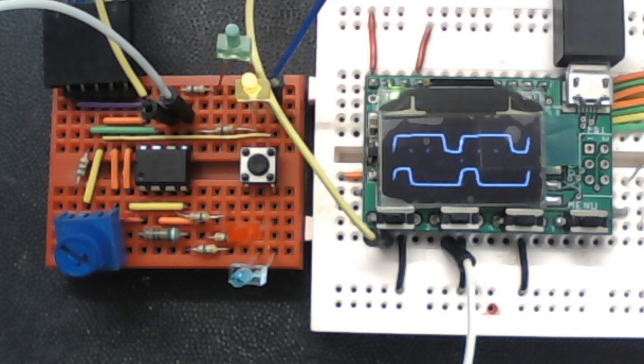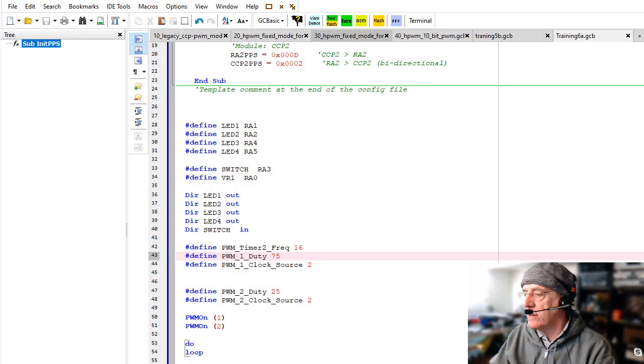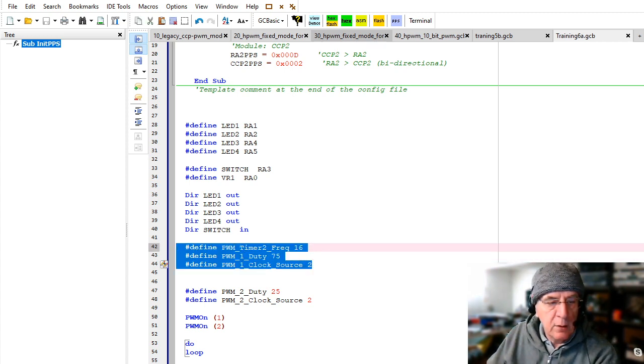That's the CCP module. But there's also included inside of here another module called the PWM module. Very, very similar setup for fixed mode. Now, what's different about the fixed mode is, remember, in the source code, it's constants, and I can't change constants as I'm running. Later on, we will be looking at how you actually make them change tomorrow. So these are constants, and they're very, very low. It's 106 words, very small amount of memory to get this operational, which is the beauty.